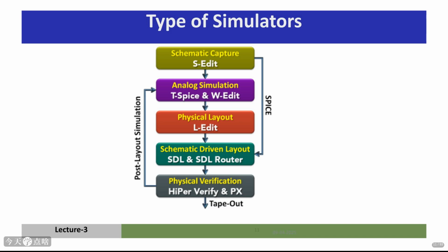Often, you'll run simulations after the layout is done, post-layout simulation, to account for parasitic effects introduced by the physical implementation. Finally, once everything checks out, you generate the masks for manufacturing tape-out. It's a complex dance, but simulation is woven throughout.